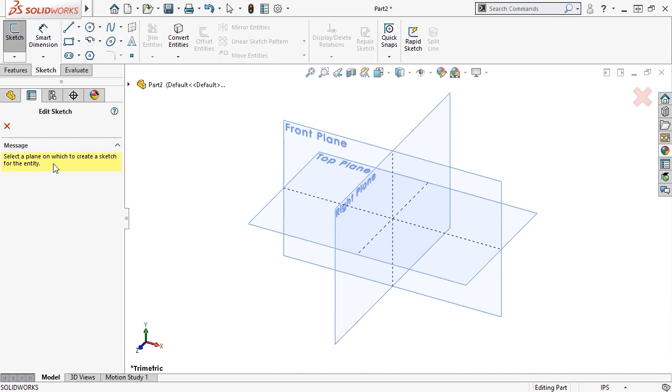Well, in the first lesson, we saw right away how two approaches could be used to create the exact same geometry. In one approach, a wide rectangle was sketched on the top plane and extruded up, and in the second approach, a thin rectangle was sketched on the front plane and extruded to create the width of the shape. Many SolidWorks parts can be created in multiple ways, so it's really up to you to choose the sketch plane that makes the most sense based on your design intent.